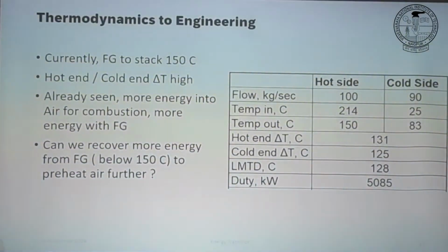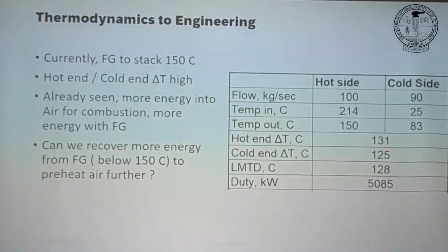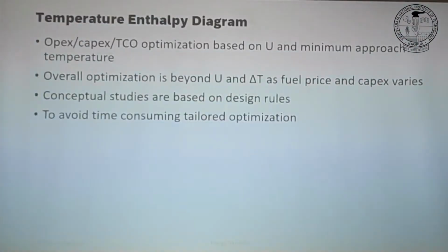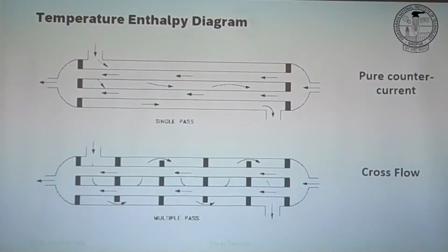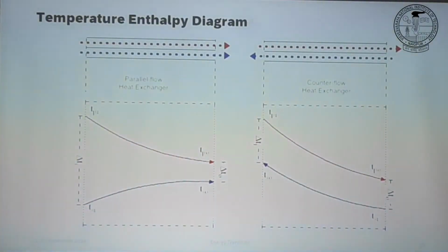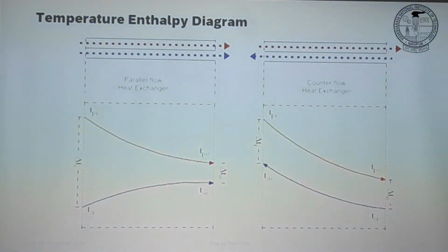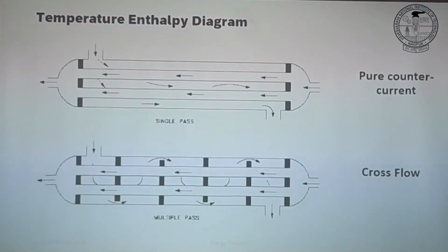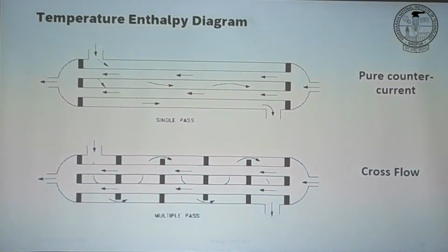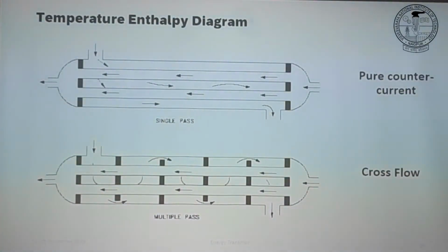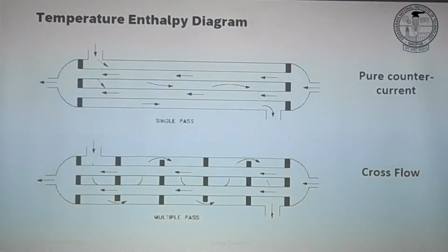Yes, we have heard of 2-4 shell and tube heat exchanger, 1-2 shell and tube heat exchanger. Is it possible to have 1-3 or 2-2? Can you share some thoughts on this front? Two tube and two shell. On the tube side we can increase the passes, but it will also change the area for heat transfer. It's just geometry and possibility of operation we have to think upon.